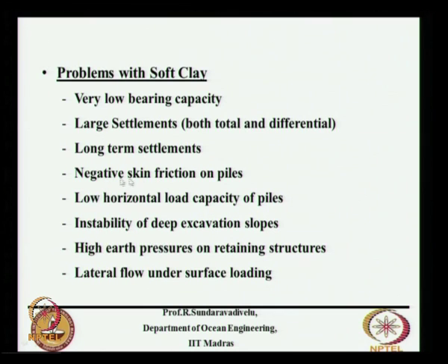There will be negative skin friction on piles, and these piles will also have low horizontal load capacity. There will be instability of deep excavation slopes, whenever you excavate there will be instability. Then there will be high earth pressures on retaining structures, then there will be lateral flow under surface loading. These are the various points to be discussed about load bearing capacity related to soft clay deposit.